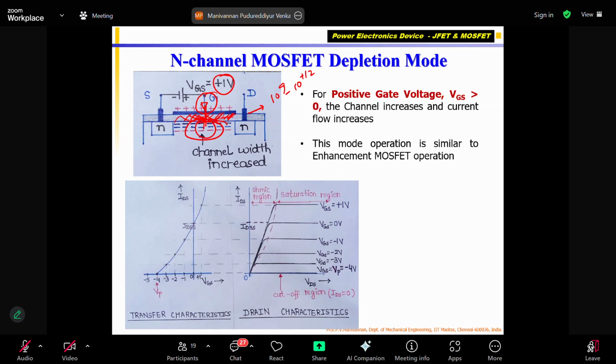Now, since my silicon SiO2, which is called insulator, is there, its resistance is very high. I say Ig, gate current, equals VGS divided by Zin or Rin of the MOSFET. Rin of the MOSFET automatically includes this number. So if my input is 5 volts, my Zin, because of the insulating layer of the MOSFET, whose resistance is 10 power 9 to 10 power 12, theoretically this should be infinity. The resistance of the silicon layer, the insulator, should be infinity.